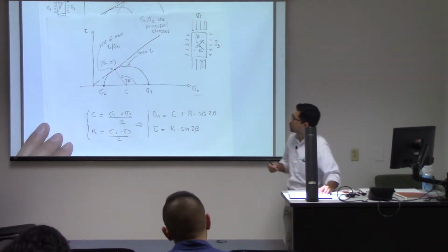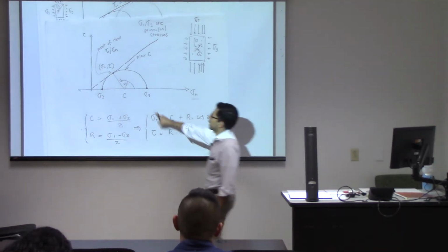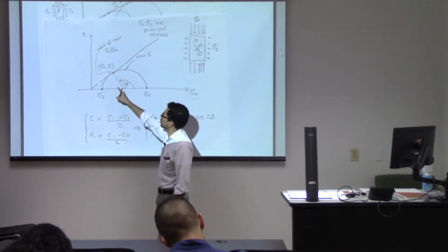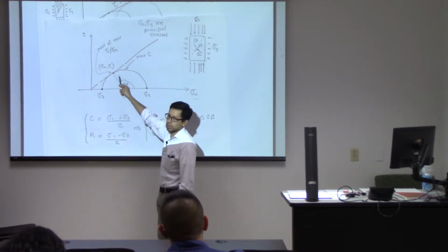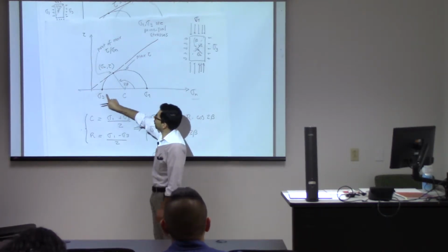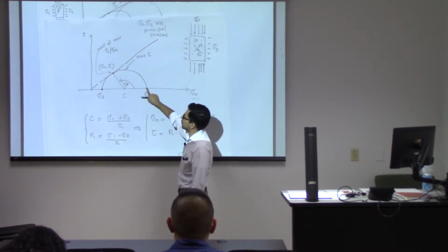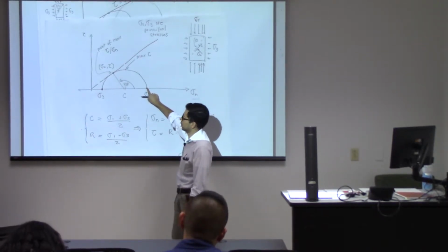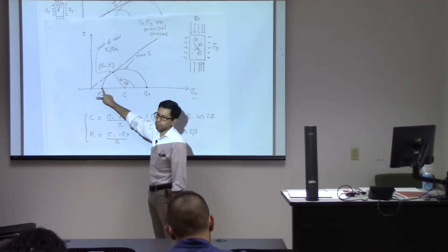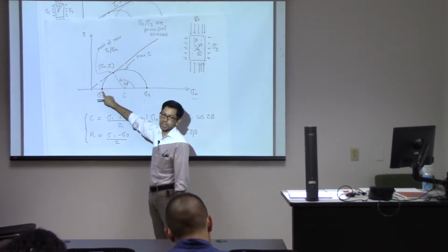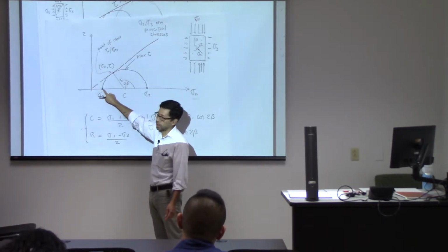Can you see that? So why is this one the point of maximum shear stress to normal stress? Shear stress divided by normal stress is just the slope of that line. So if I had a point, for example, over here, it has zero shear stress and it has a huge normal stress. But if I had a point over here, it has a small normal stress, but still has zero shear stress.